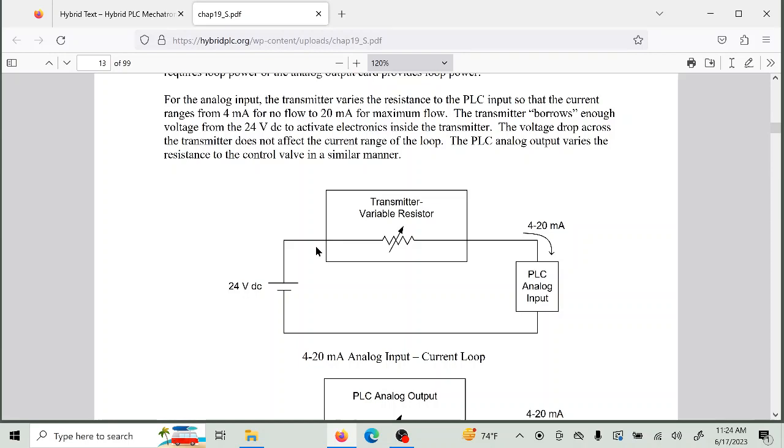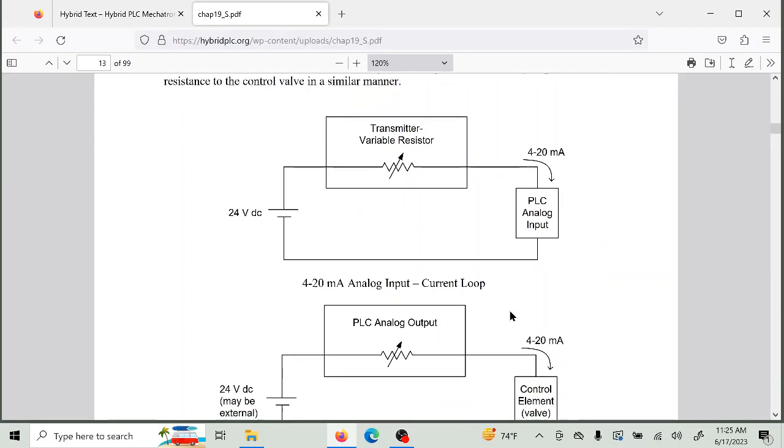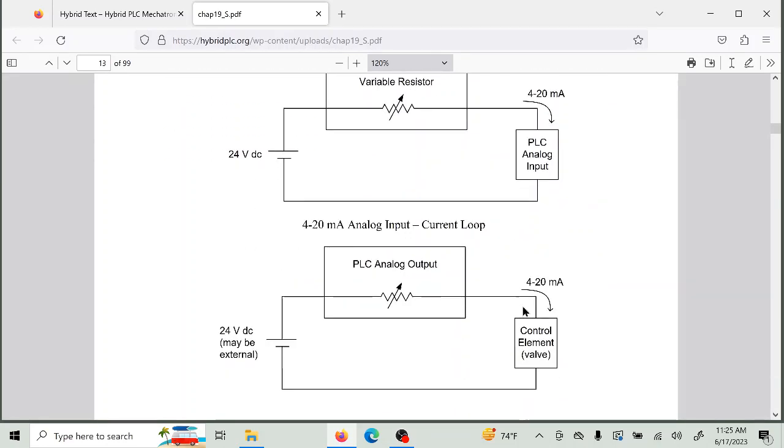So on a 2-wire system, you use 2 wires to go out there and you bring this back, and on that 2-wire system, you have a 4 to 20 milliamp signal that's using unshielded twisted pair wire in a separate conduit. And when you bring these back to your PLC, you do not land them on terminal blocks. You put them straight into the input of the PLC. So that's important that you do that, and always keep your DC wiring or your analog wiring away from your AC wiring or your 110 or your motors, especially your motors.